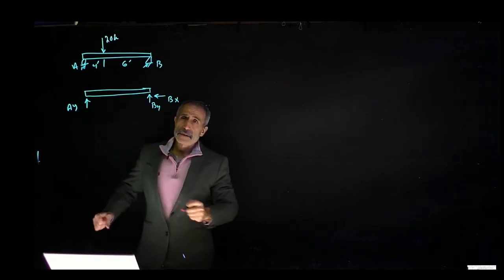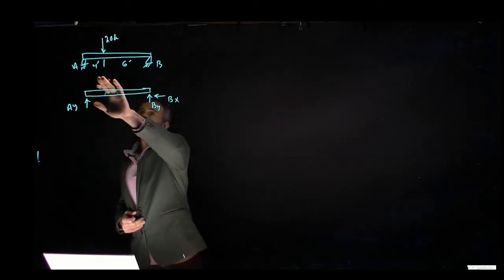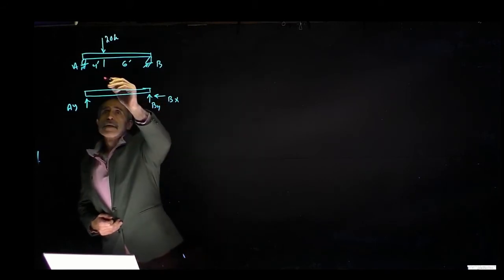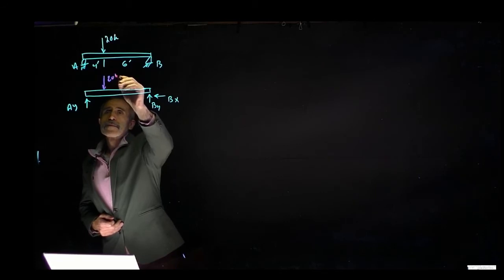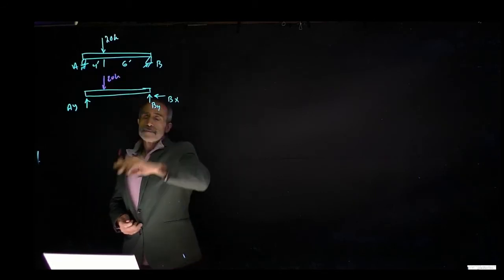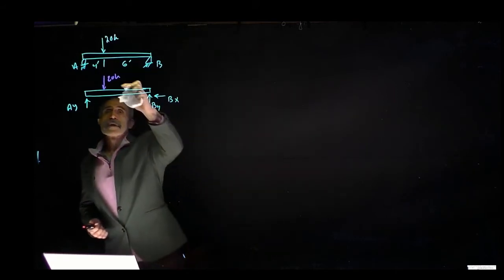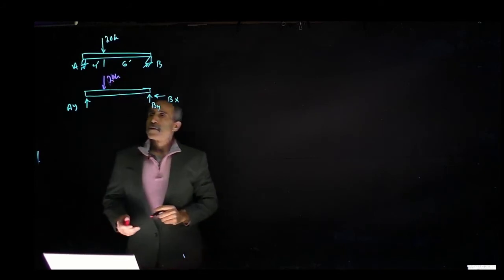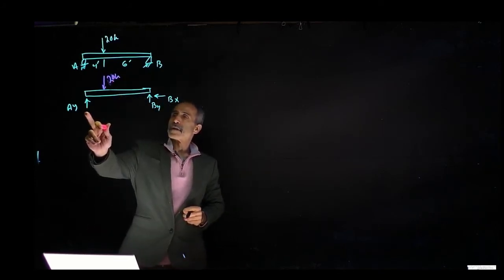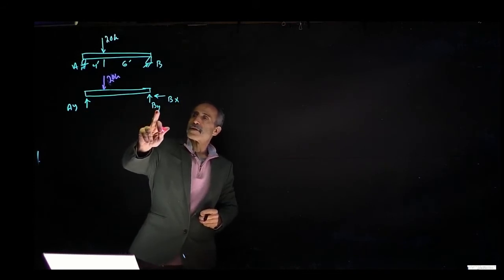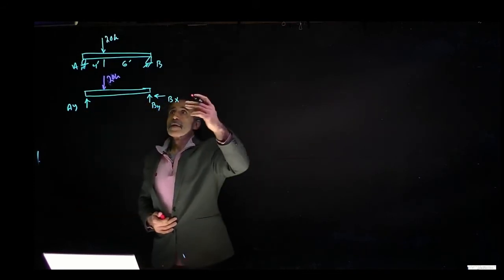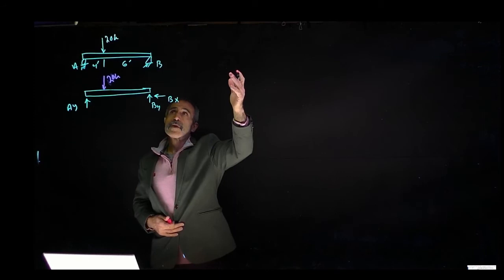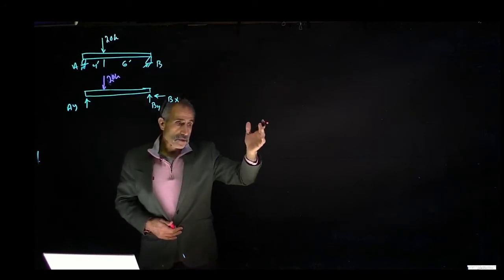We can do this graphically first, but before we go ahead, let's calculate the reaction forces. When we do a shear free body diagram, this will be our load, 20 kips. So we have these reaction forces here, and a load. And we talked about the three equations of equilibrium, which was summation Fx equals 0, summation Fy equals 0, and summation moment about any point equals 0.